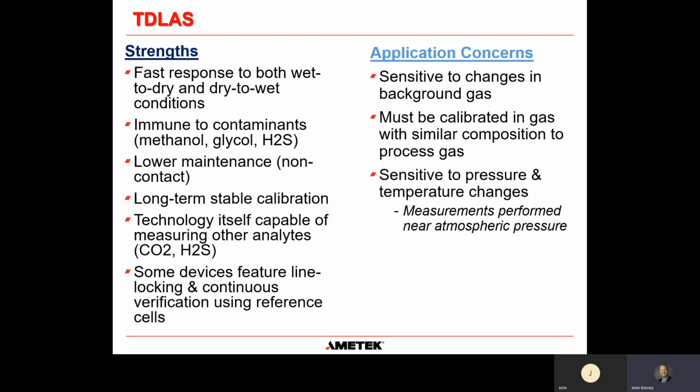As I mentioned, the laser beam scans across a wavelength, and you can pick and choose which laser you want. And you can actually measure not only water, but with other laser wavelengths, you could measure other analytes, such as, say, CO2 or oxygen or H2S or anything like that. So the technology itself does have the capability to measure other analytes. That doesn't mean necessarily one laser can do all that, but the analyzer technology itself could do that.